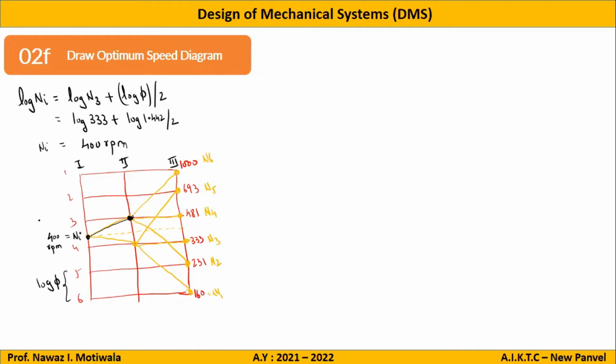Correct. Tell me other options too; you have studied this before, in Theory of Machines, Machine Design 1 and Machine Design 2. I have one mechanism running at 1440 RPM and I want to reduce it to 400 RPM. So what should be in between? What mechanism will we use? We will increase the gear diameter, on the output. So you mean to say on the motor output shaft you will put a big gear so that its speed is reduced. Yes sir. Okay.